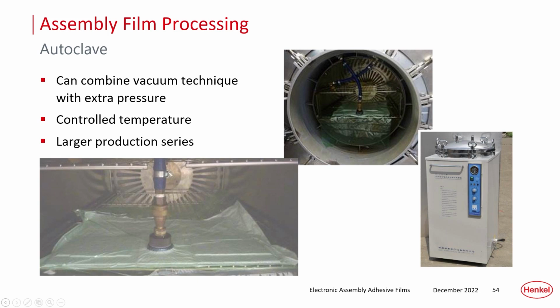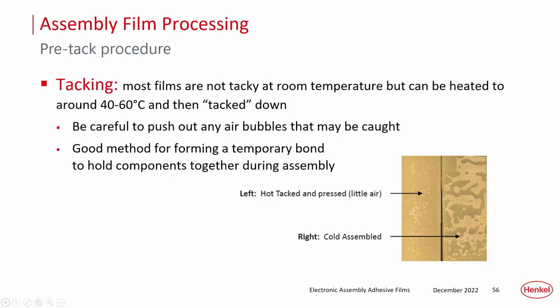And the final option on the next slide would be, if the parts are relatively flat, to use a programmable heated vacuum press, so that you can program this to apply pressure, initially vacuum pressure, but then to apply the heat and compression during the cure. And people do that. There are many thousands, maybe millions of parts that have been built with that sort of system. So that's an option also. Okay, next one.